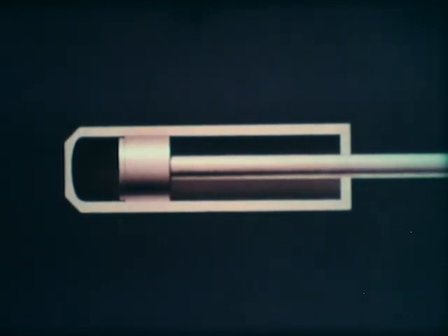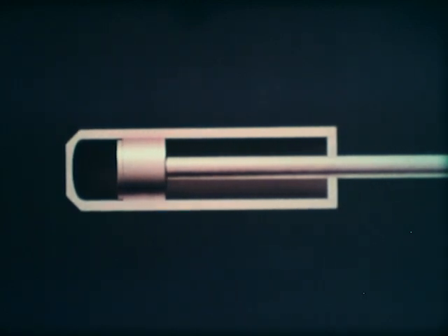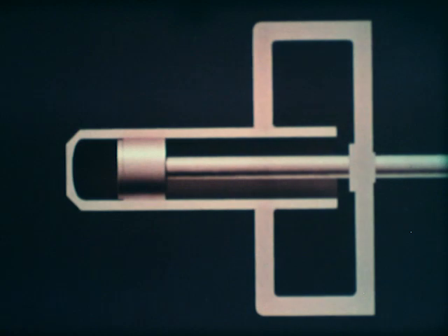So far it has been assumed that the pressure to the right of the piston remains constant throughout the cycle. This doesn't apply in practice. The volume to the right of the piston obviously changes. So does the pressure. However, the pressure is kept reasonably constant by including a cavity known as the buffer space. The power of the cycle has been raised. Let us now turn to the efficiency.